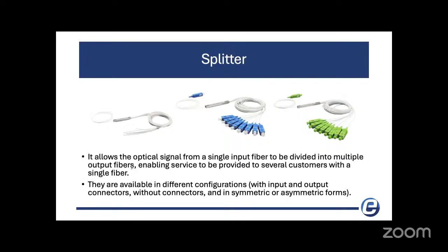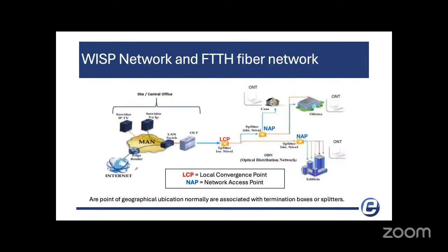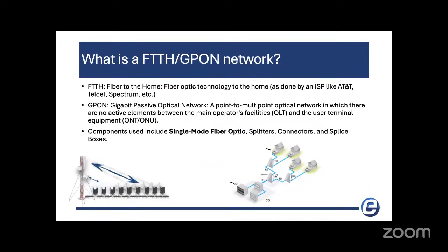When you're doing this type of installation, you go from here, you have your trunk, and then you use a splitter from 1 to 4. Even if you don't use all 4 lines, you can use this one. So it goes through here, and then I have 8 houses there, so now you go 1 to 8. And every one of these is a subscriber. Even if you don't use this connection or this connection, it's scalable in the future. If you make any other connections, you can take your line from here and do another 1 to 8 splitter. So you can split again.